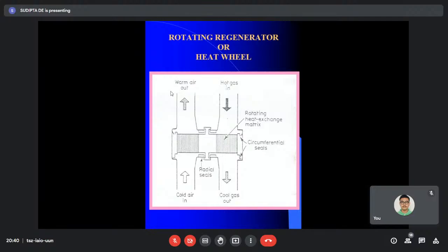because if you make it very fast, then no heat transfer can happen and effective time will not be there. But if the wheel can rotate continuously at a very low RPM, then what is expected? The batch process is replaced by a continuous regenerative heat exchange process. Rather, regenerative batch heat transfer or regenerative continuous heat transfer process. In industrial applications, both examples are there, but generally the continuous process is more common.